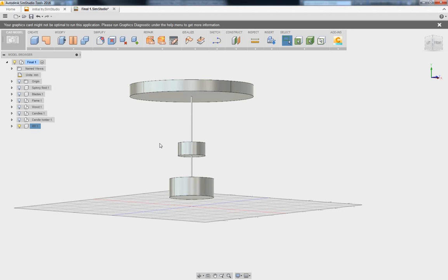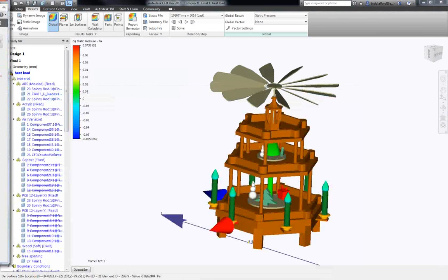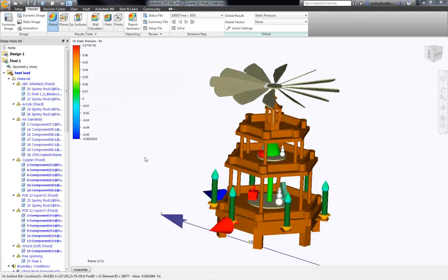Todd then went back and changed his rotating region so that it encompasses even the shaft that connects the 2 layers that rotate with the actual fan blade, which are driving the, in this case, it's technically turbo machinery. Okay. So that's that.